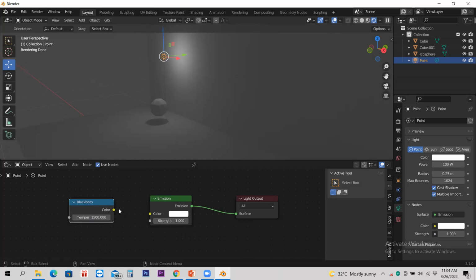It says temperature 1500. It's a color thing, so just click and drag this thing and connect it into this color. Now this 1500 temperature is applied to this light fitting. So what you see is that color. Okay, once you complete, just tell me. Yes, sir. Okay, great.